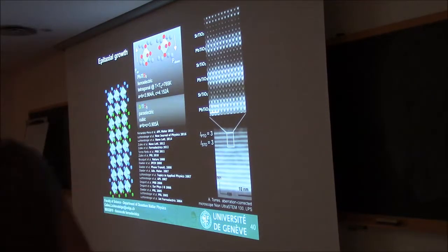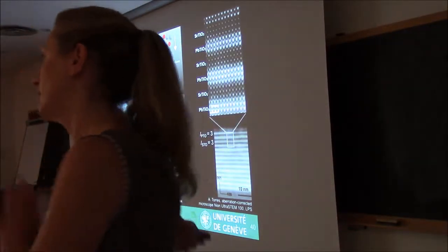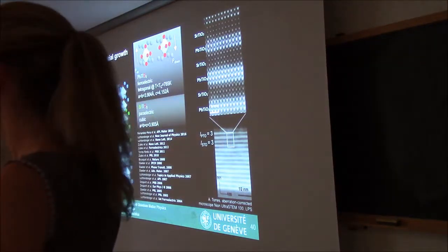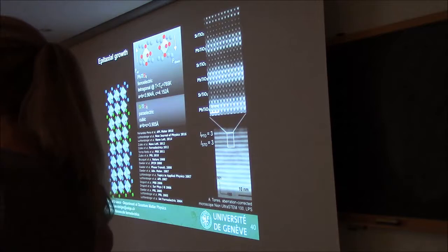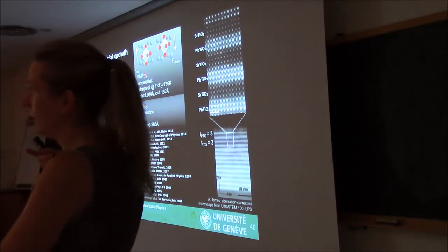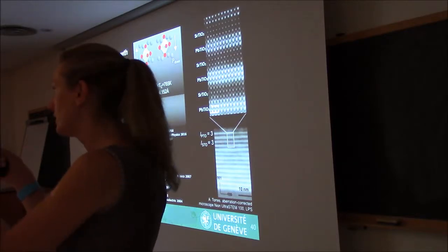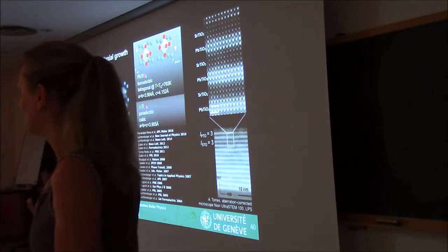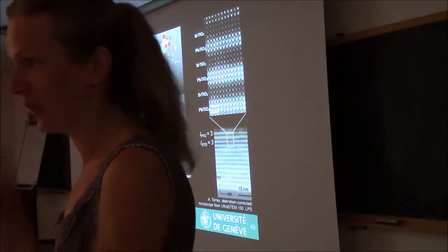So yes, and even in the group, we built several of these sputtering systems because in all of them we grow different materials, but also, for example, we grow strontium titanate in many of the different systems. For each system we have to change the temperature a bit, because the thermocouple that measures the temperature is not exactly at the same position. And as in cooking, you don't control everything, but once it works, it works very well.